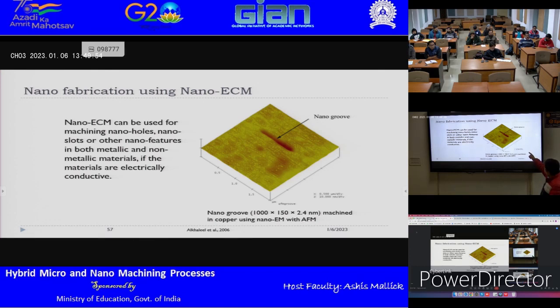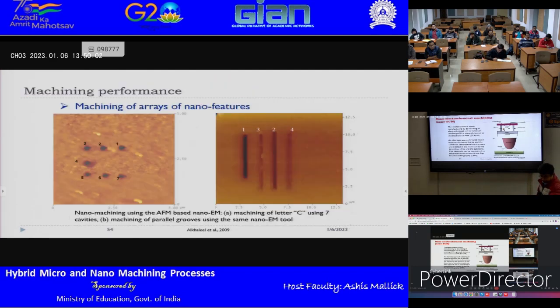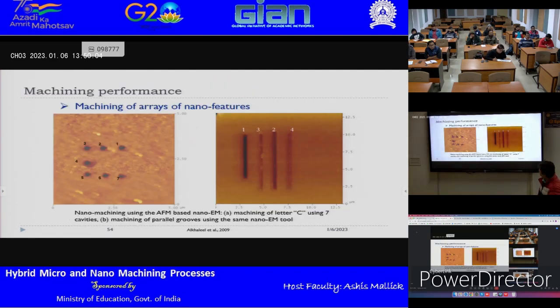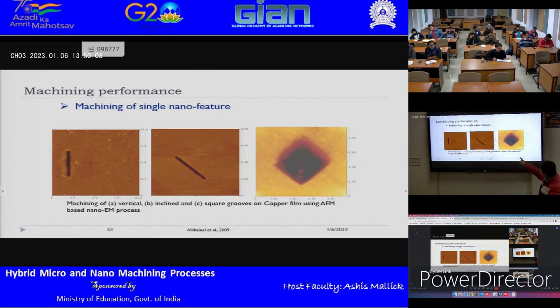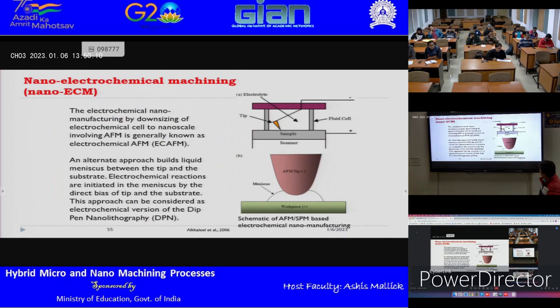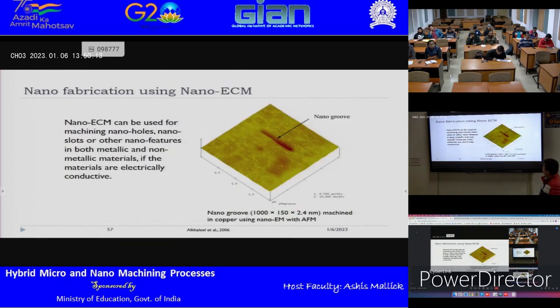You see, the electrochemical dissolution also makes the edges not so sharp. For EDM it was sharp. If you just go back a few slides, look, yeah, the first one, look here, those are very sharp, right? The edges. On the other hand, for electrochemical dissolution, same problem, it is not sharp, okay? So the ECM process doesn't really give you very sharp corners.